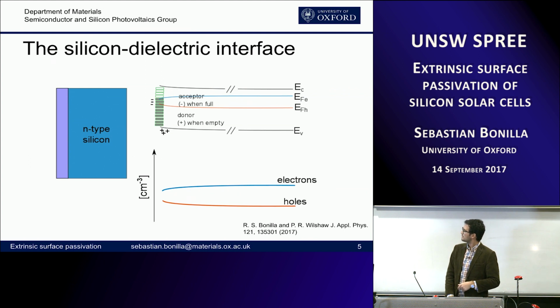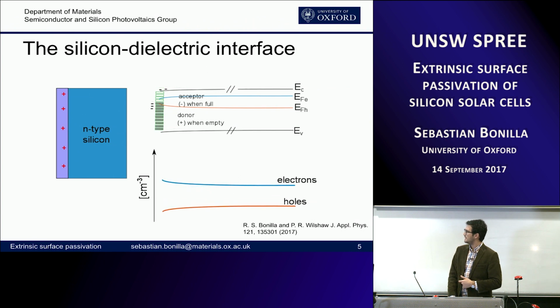Right. So then, when we go and try to passivate this using field effect, using charge in the dielectric coating, the first thing that happens as we put charge in that dielectric coating is that some of that charge gets compensated not only as a space charge region, but also as charge in those interface states. So here I've schematically put, say, 5 charges there, and we see 3 of those charges are actually compensated in the interface states, while only 2 are compensated as space charge region.